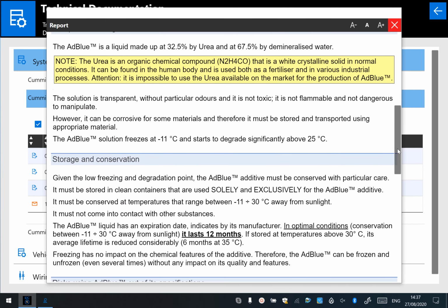As long as they're programmed to the ECU and they're electronically read, we can look at them. For example, a lot of these are static, and because we're in a test program, there's not a great deal we can do, but we can double click those to create a line diagram. Very useful if you're doing things like wheel speed sensors. You can watch a peak and a trough in a line diagram.